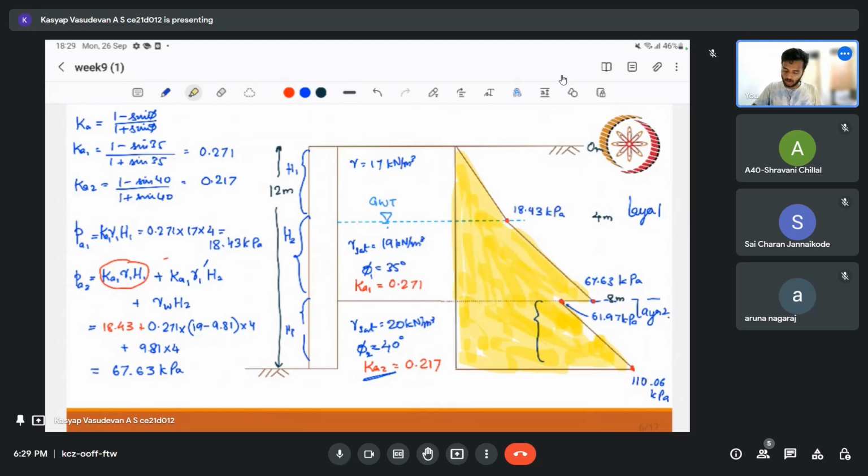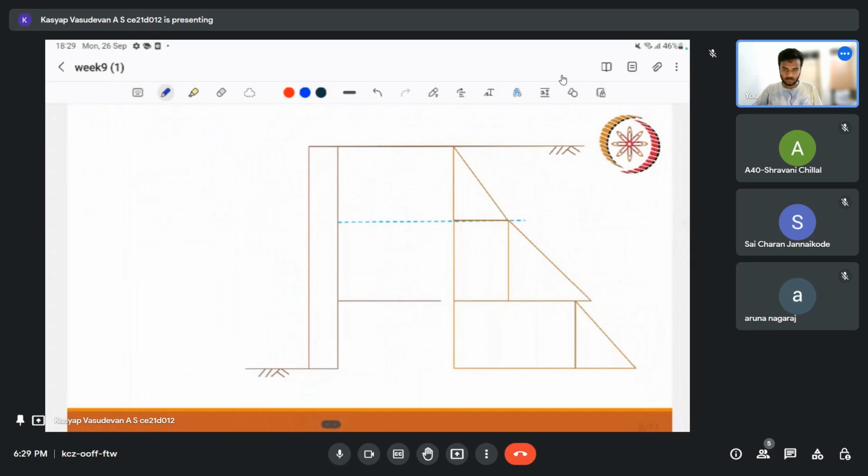But when we are doing a trapezium, we need to find the centroid also. That is also a challenge, but there is a formula for that. So we have to find the area of one triangle and two trapeziums. Then we have to find the centroid of the area, or we can divide it into different sets of rectangles and triangles. So I can divide that into different triangles. So let me just write the values here so that I can find the area.